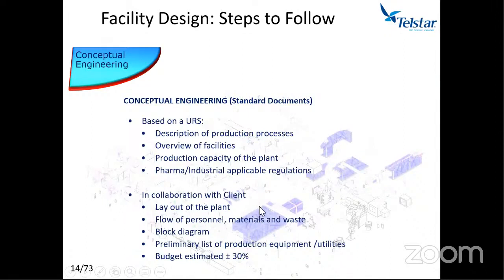Again, I like to explain that in one of our projects, we were thinking of how to bring everything to the end, but we skipped something because the client did not mention it, and we were not thinking at that moment about the sampling plates that will be used in the area. And quality control was very far away. So we had to redo part of the design because we didn't think initially about how to bring the sampling plates for microbiological control to the area. Once this was redesigned, we had a very nice flow with everything being considered.